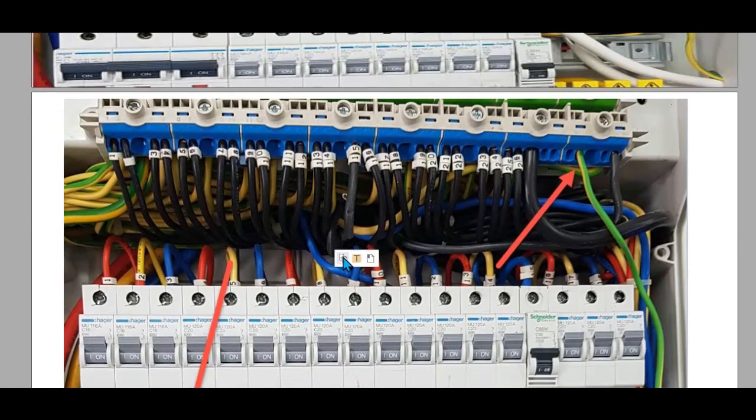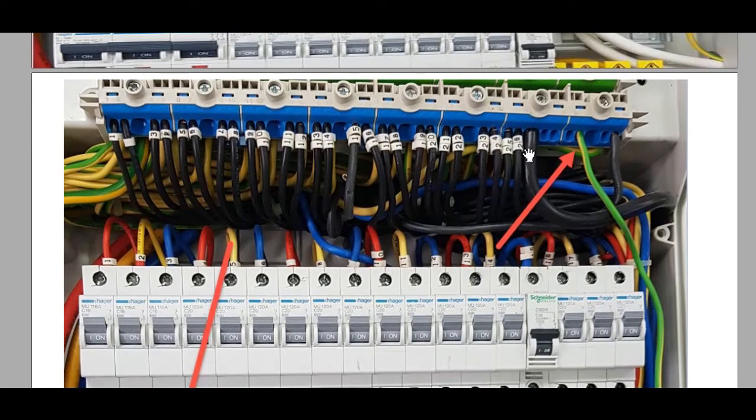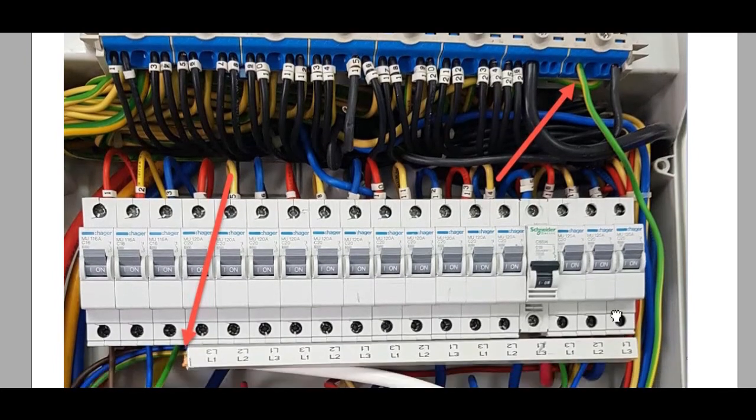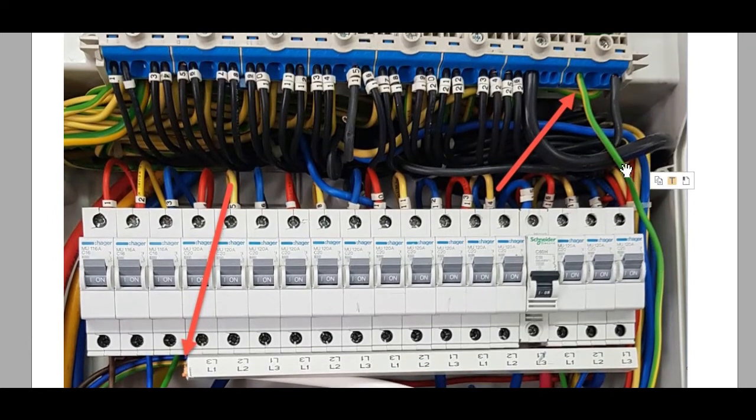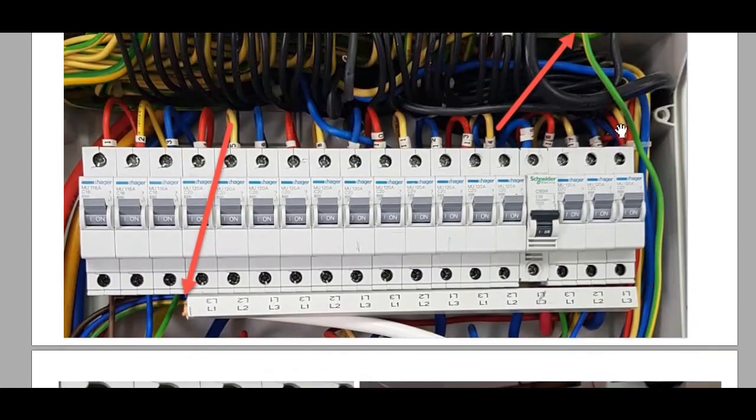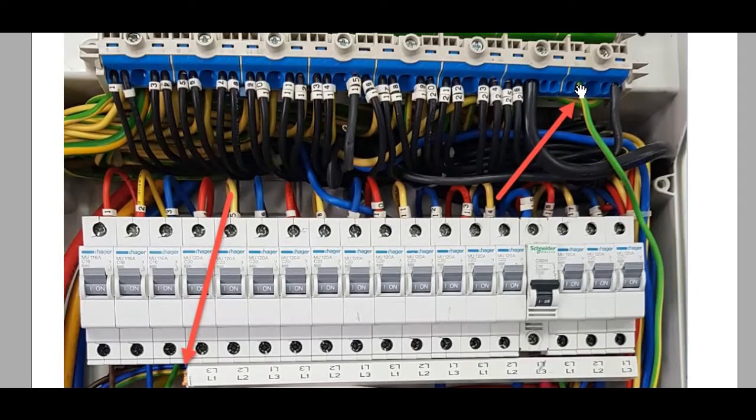This first. The second one, as you check here, this is the bus bar for the neutral. This is a neutral bus bar. This is the blue one. What they are doing, they used the earth wire and connected it to the neutral bus bar to send the neutral conductor to another place. So it must be this wire, not the green-yellow wire. It must be a black wire. Otherwise, they can use black tape for all the wires and tape the wires in black. So when you are going to inspect, we will check it as a black wire.